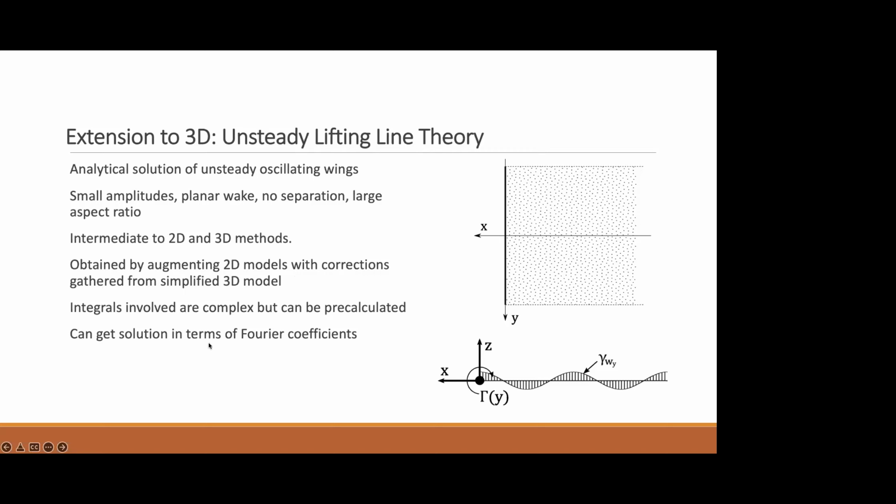And just as in unsteady thin airfoil theory, we can get the solution here in terms of Fourier coefficients, which are very useful to predict and model leading edge vortex formation and so on.